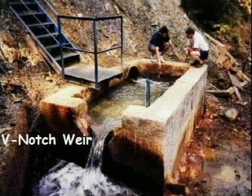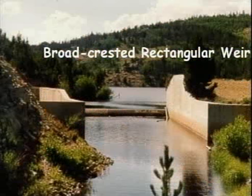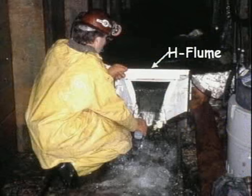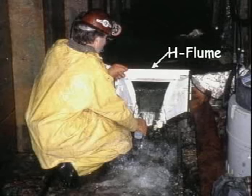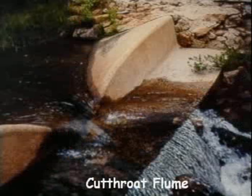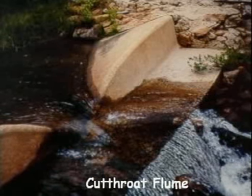Here's a V-notch weir measuring flow diverted from an underground mine shaft. It's pretty easy to get a sampling point. Here's a broad-crested rectangular weir tied into a spillway from a reservoir. Here's a fiberglass H-flume that was installed in an underground mine portal. The flow at this site ranged from about 15 gallons a minute to over 600 gallons per minute. It's made out of fiberglass. Here's a cutthroat flume installed on a natural stream, and it's made of concrete.